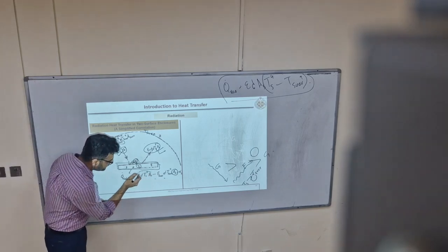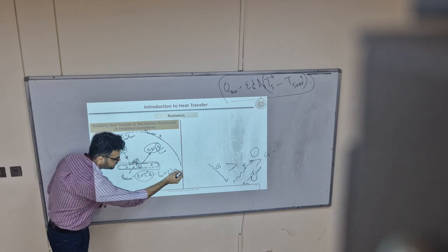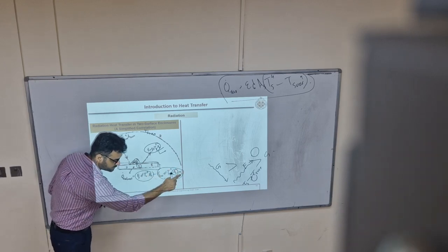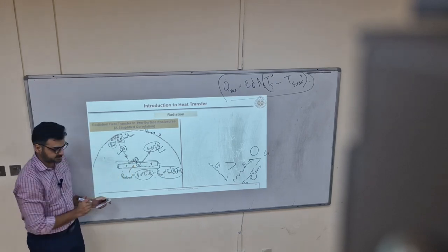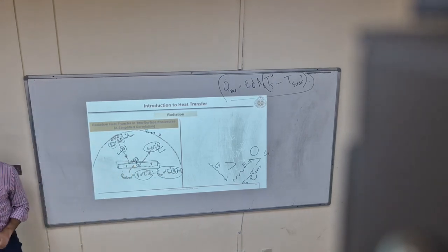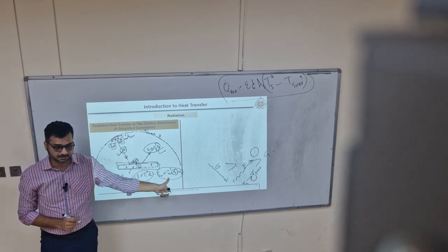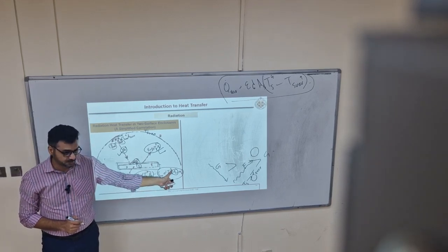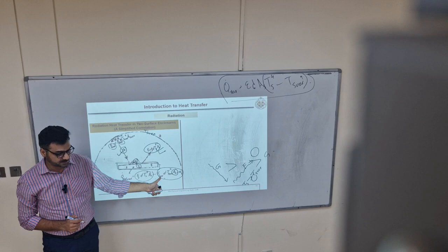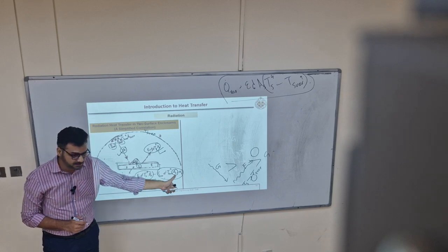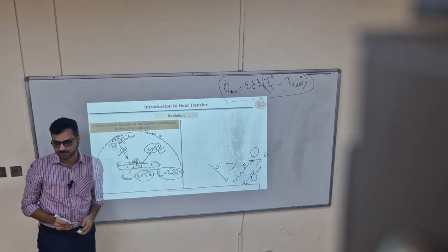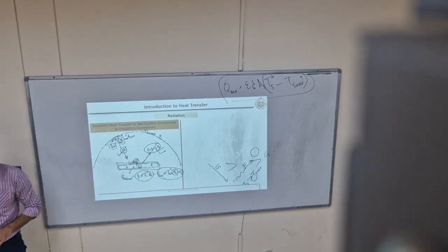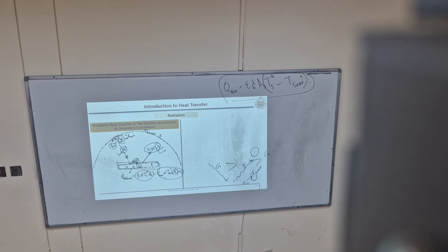This is leaving the surface. This is absorbed on this. Why absorbed? Because I'm multiplying with the absorptance of that surface, S. But that is coming from the surrounding: surrounding temperature to the power 4, surrounding emissivity. But the area is not the surrounding area. It is the area over which it is falling or absorbed. This equation is clear.